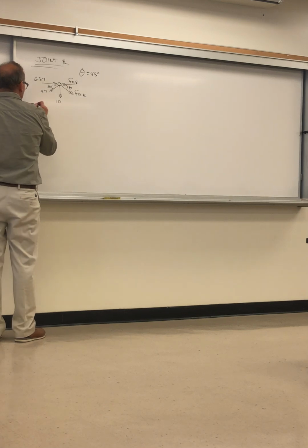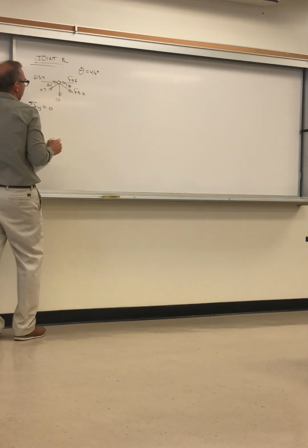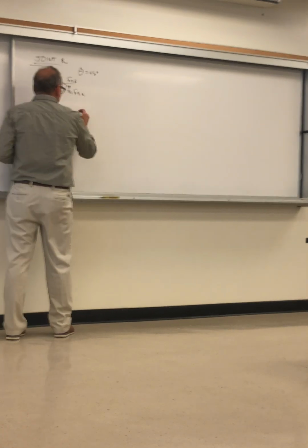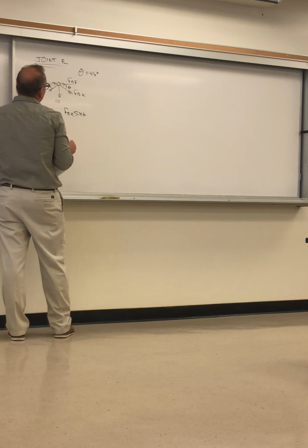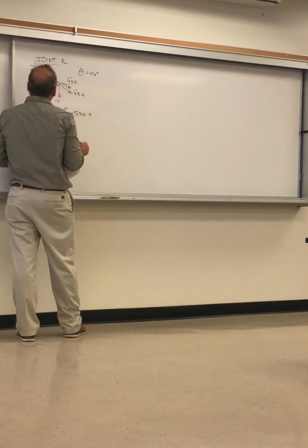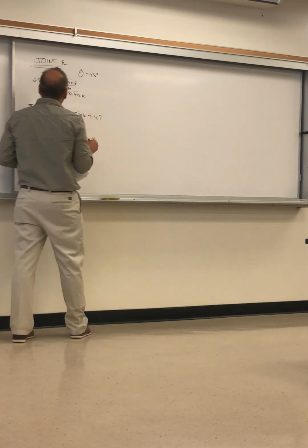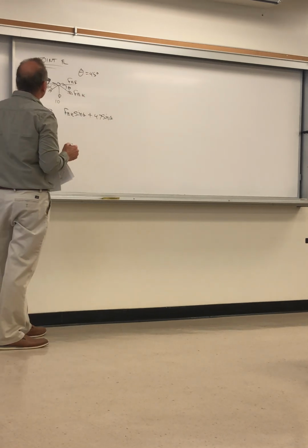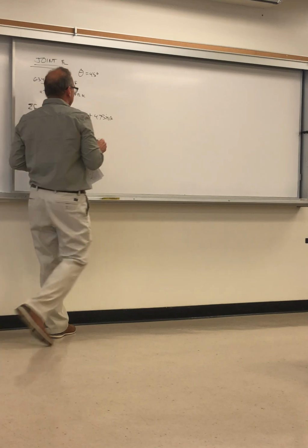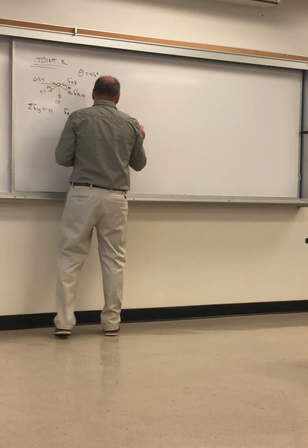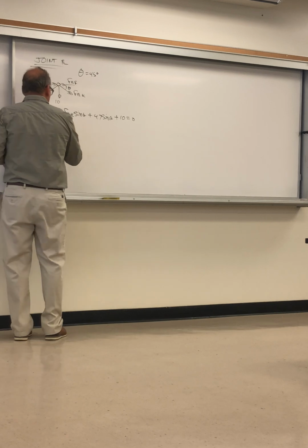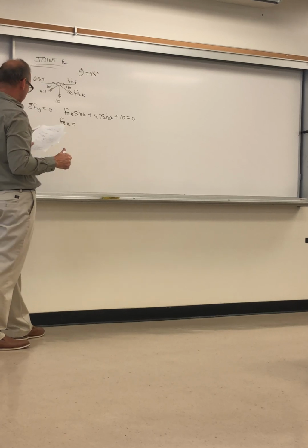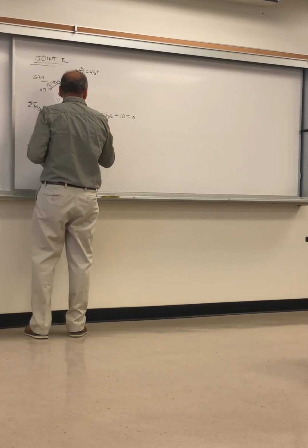So let's start with summation of forces in y equals 0. I have F of EK multiplied by sine of theta, plus 4.7 multiplied by sine of theta. So this is going down, right? Plus 10 is 0. So we get a negative F of EK, and I take all that to the other side and divide by sine, so I have a negative, which is minus 18.8. Okay.